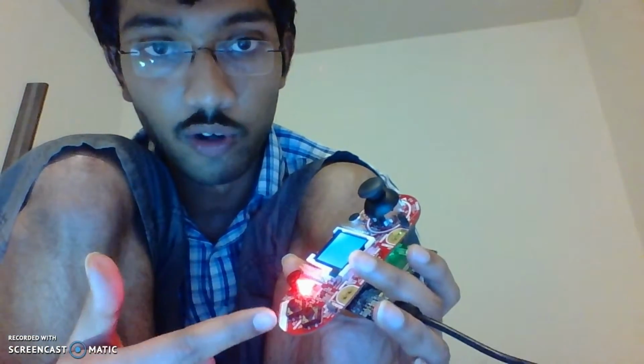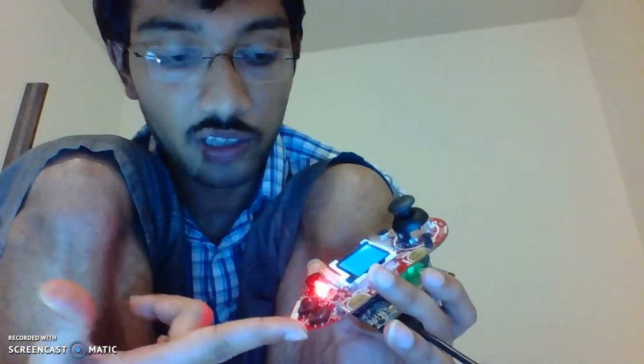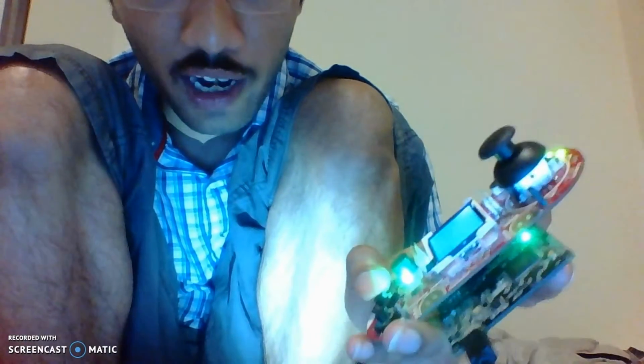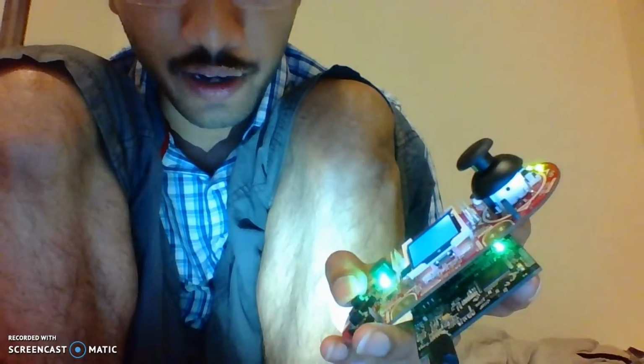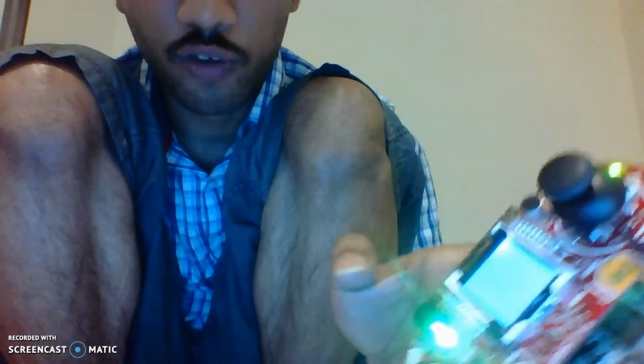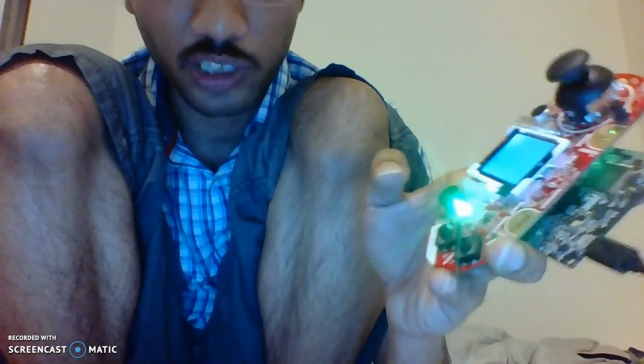Now let me present the priority of burglar and fire alarm over the doorbell. Hello, hello, hello. Now you see, even when the doorbell is being emulated, if I make a sound that is greater than the threshold, the burglar alarm is being emulated. Let me now show you the priority of fire alarm over the doorbell. Let's press the doorbell and bring the mobile phone near it just after I press the doorbell. Now you hear that. For the first 2 seconds, we heard the doorbell, and after that, we heard the fire alarm. That's because the fire alarm is a higher priority.